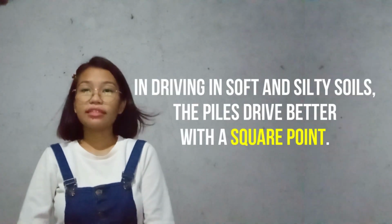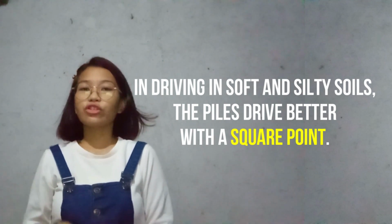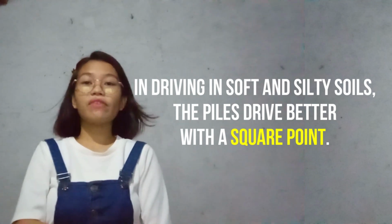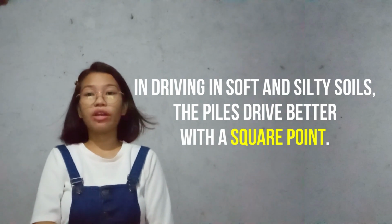When driving in soft and silty soil, it's better to use a square point. This is usually in the form of a cast conical point about 5 inches in diameter, secured by a long dowel with a ring around the end of the pile.